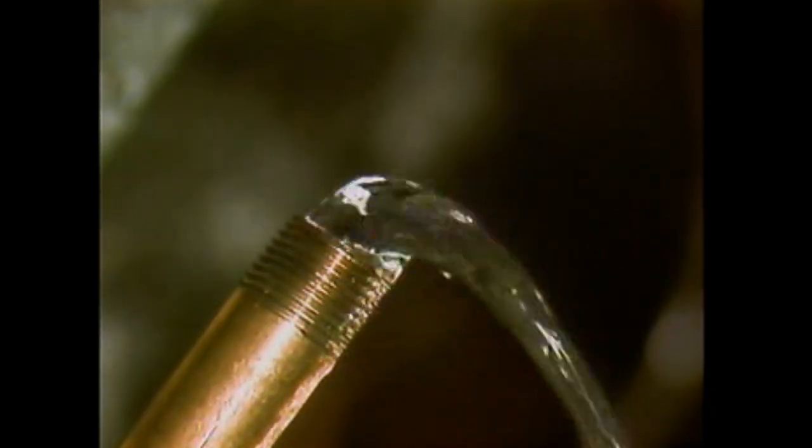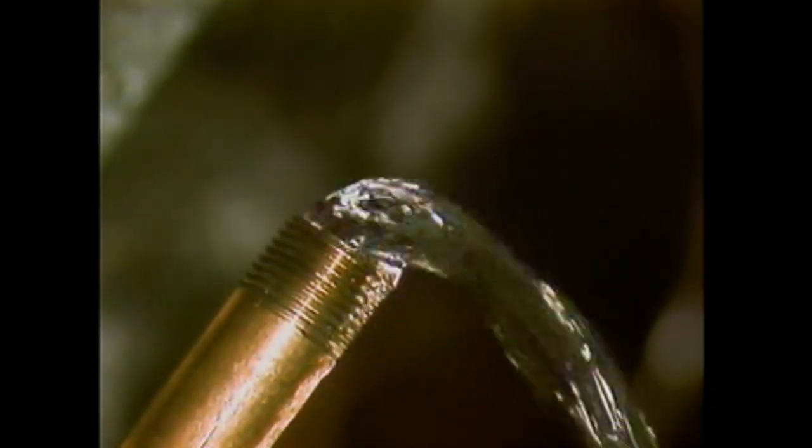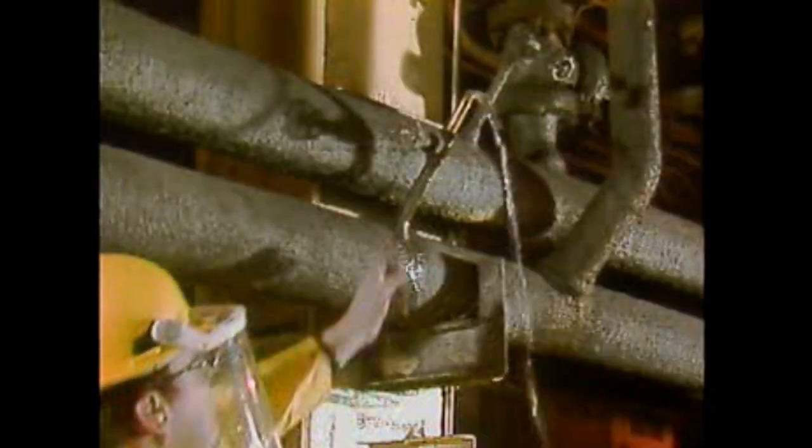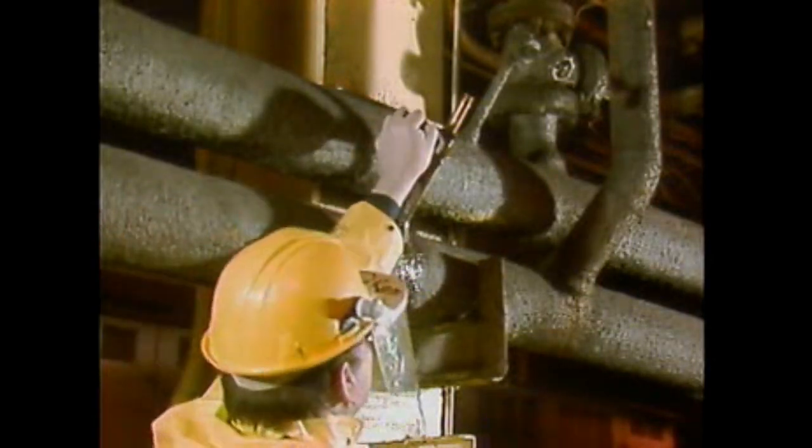A steady stream of liquid from the vents indicates that the system is full of liquid. The operator then closes the vent valves. Not all vents are open to the atmosphere. In some systems, vent piping is used to route escaping air and liquid to a containment vessel or a treatment system. When vent piping is used, the operator can determine whether the system is full by touching the vent pipe. If he feels vibration caused by fluid flow, he knows that he can close the vent valve.